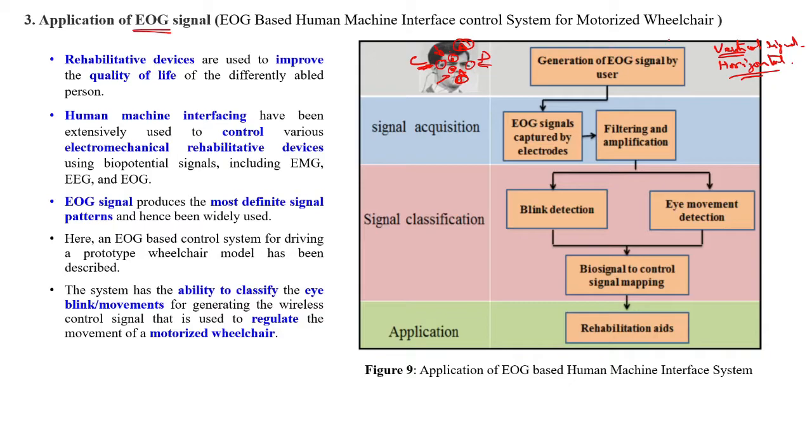A and B, it will take the differential signal and generate the vertical signals. Similarly, if you take C and D, it will give you the horizontal signals. So what operation is happening? Here the biopotential amplifier finds A minus B or B minus A, and here it finds C minus D. When you are moving in the vertical direction, this A minus B is larger. When you are moving in the horizontal direction, the C minus D value of the potential will be detected.